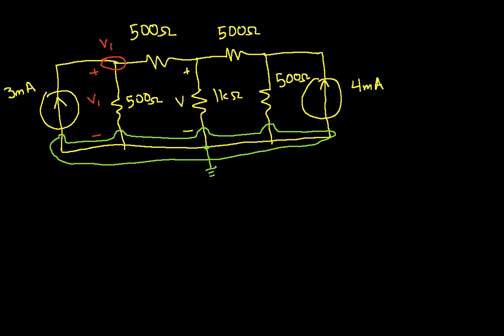That voltage will be V1. Now, when we start doing this, we're not going to explicitly indicate every time we say V1 that it's the voltage between this node and my reference node. The idea that it's the voltage between a node and a reference node is implied. In a sense, the reference node plays the same role as sea level, for example, when you're looking at altitude. You can say that Phoenix, Arizona, where I live, is at about 1,200 feet altitude, and what that really means is that it's 1,200 feet higher than sea level. But you typically don't mention the above sea level part.